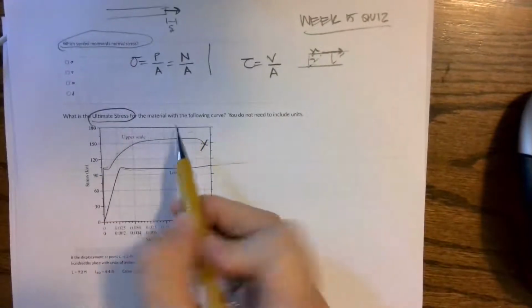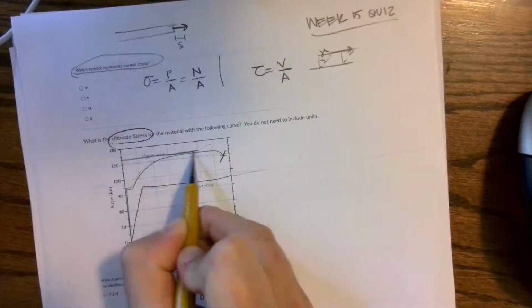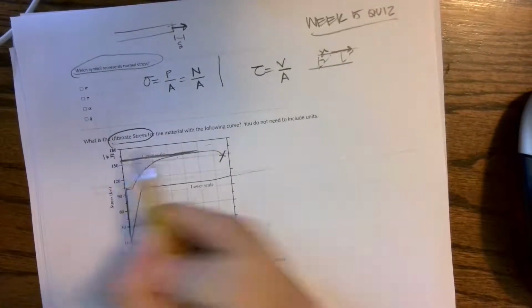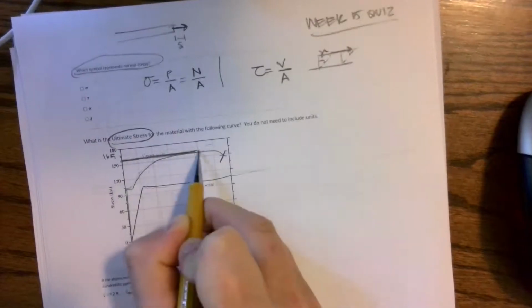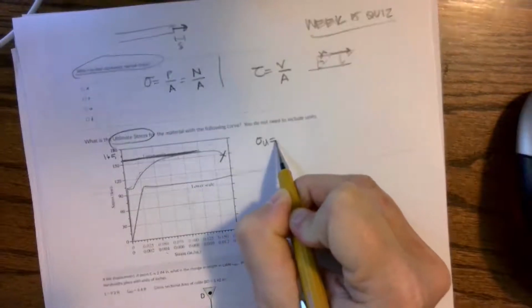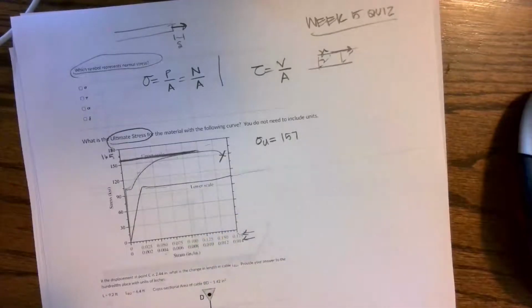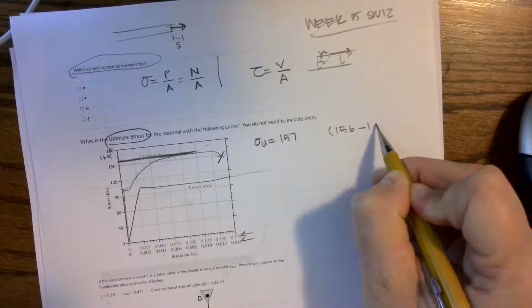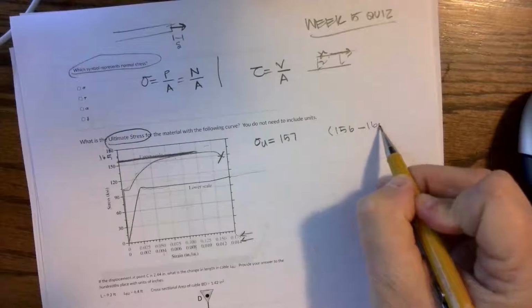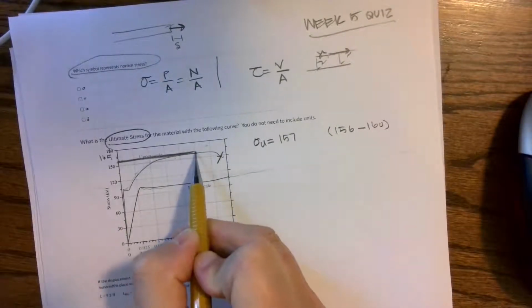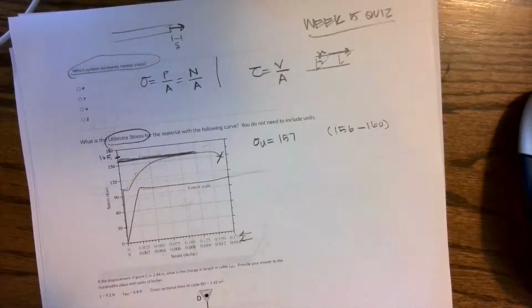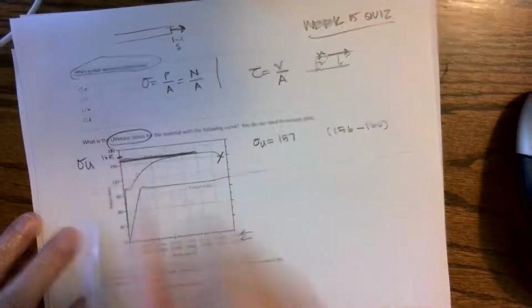So if I want the ultimate stress, it's right up here at the top. Ultimate, and that's 150 to 180, so I know that this has to be 165, and we're kind of here in the middle, so I'm going to say my ultimate is 157. I have a range on these types of numbers, where I probably said like 156 to maybe 160, something like that. It should be in that ballpark. If you come back, you can see it's about halfway between 150 and 165, so ballpark about 157, 158. That's my ultimate stress.